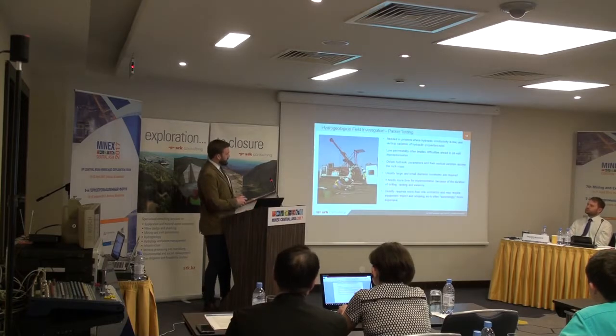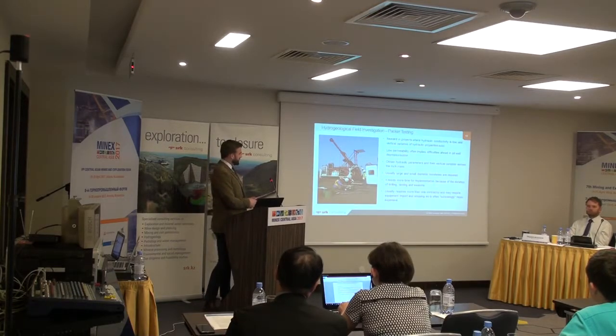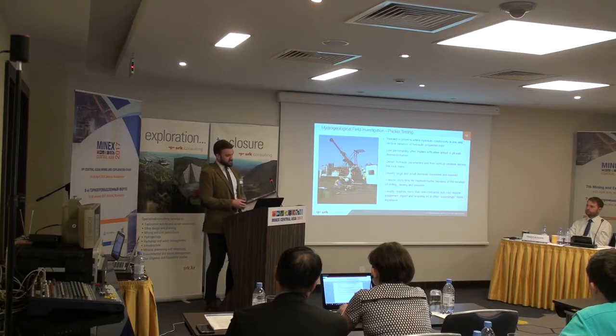This is a packer test that we carried out on a project in a 55-degree inclined angle. And it's needed in projects where hydraulic conductivity is low and vertical variation exists.